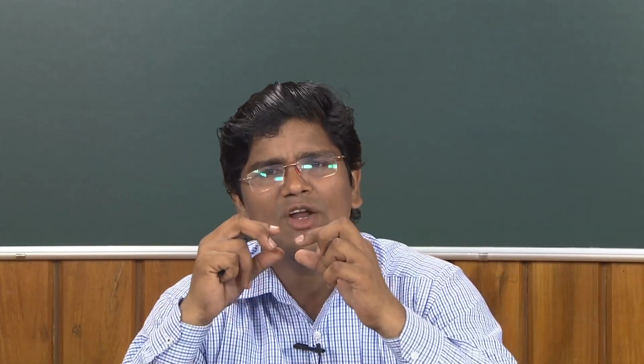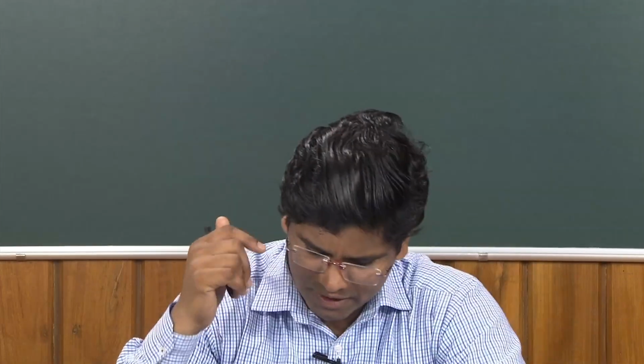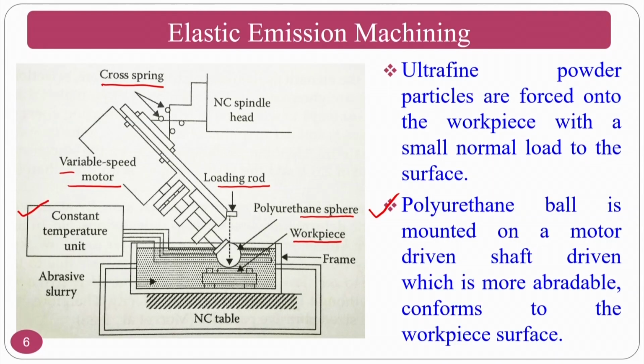Normally, whatever the temperature that you are maintaining here, it may not happen, but there may be, because your focal point will vary if there is thermal expansion and contraction. So, in order to maintain all these things, you have to always go for a constant temperature unit. If there is a contraction and expansion at a sub-nano level or a nano level also, the focal points will drastically vary. So, for that purpose you have to maintain the constant temperature.